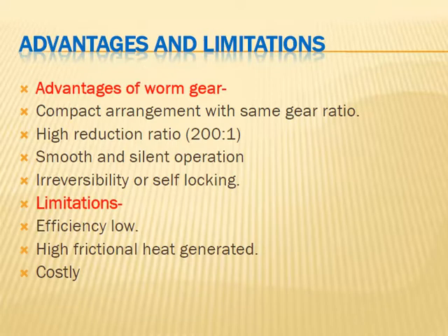Worm gear drives have various advantages. Worm gear drives are compact compared with spur, helical and bevel gear drives for the same reduction ratio. As it is compact and a space saver, a very high reduction ratio can be achieved.